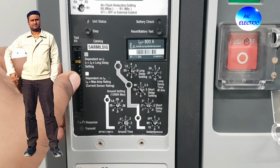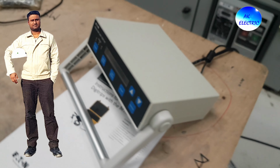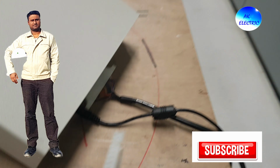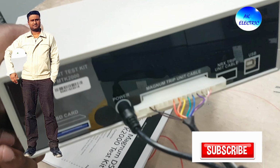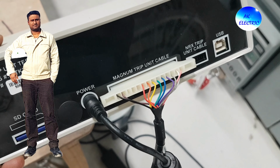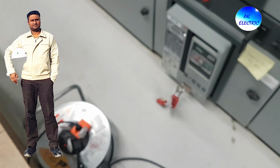First, for a secondary injection trip test we have to connect our secondary injection trip test unit. Here you will have this 8-pin plug, and this is the power unit. We have a Magnum trip unit cable on one side, and the other is the power cable, which you can connect to 230 volt AC.